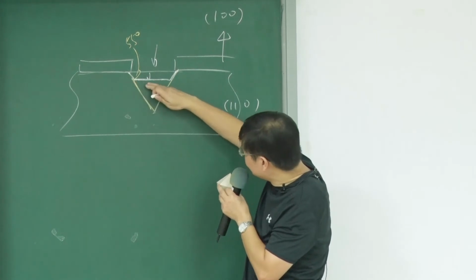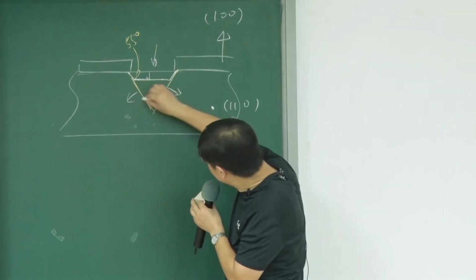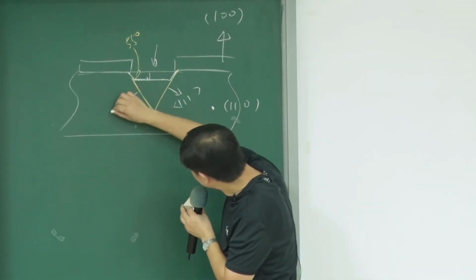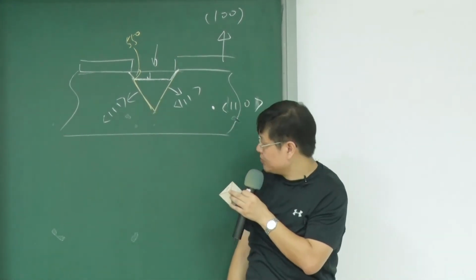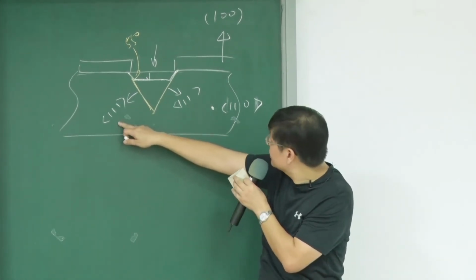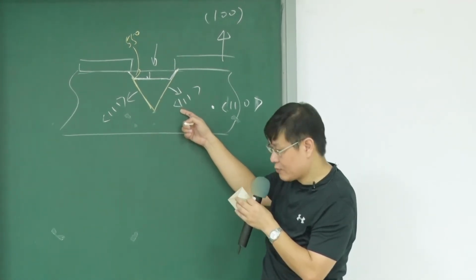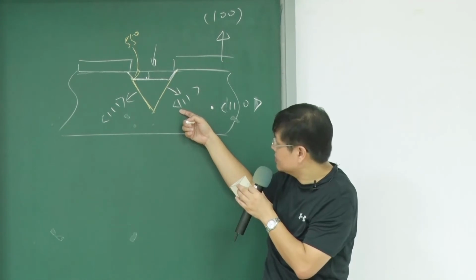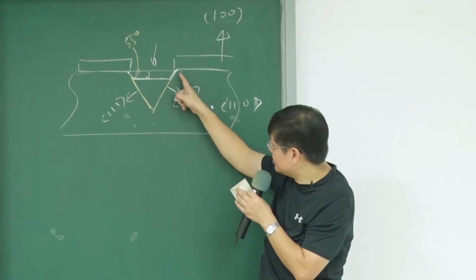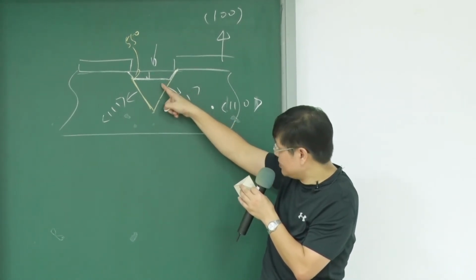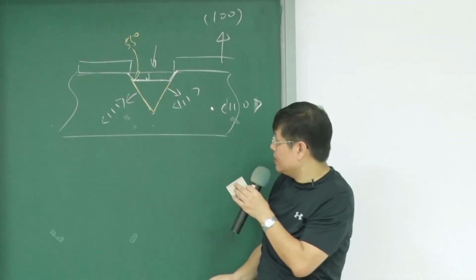Okay, so this is the first time, maybe after 1 minute of etching, you got this structure. So you have a flat surface on the bottom, but your boundary has been confined by these two 1, 1, 1 surfaces. Okay, we use this kind of notation. That means the direction. This means the surface. This means the direction. So these two are 1, 1, 1 surface directions. So be confined. So after 1 minute, you see these results. So the boundary will not be beyond the final shape. Okay, so this is the first step.